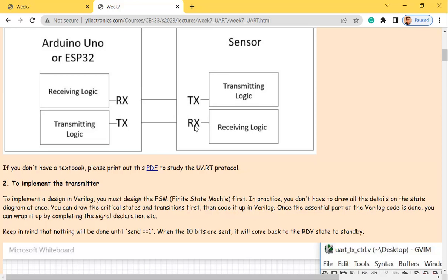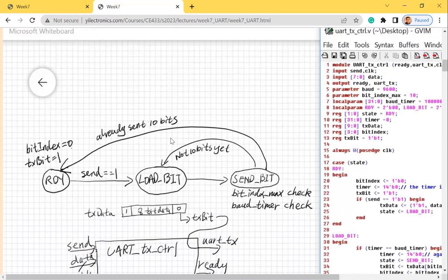Why do we have to do that? I mean, TX is not doing anything, right? So I think the module here is ready to receive something, so it probably doesn't want the two modules running at the same time. Yeah, I meant for the other module, because you don't have the physical pin here, do you? It's just 2 lines, yeah. So actually it's being used for the RX in the same chip.